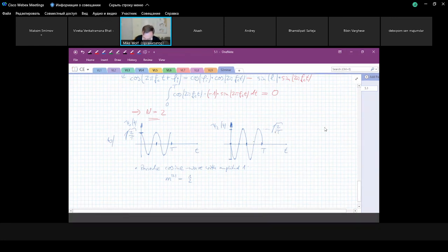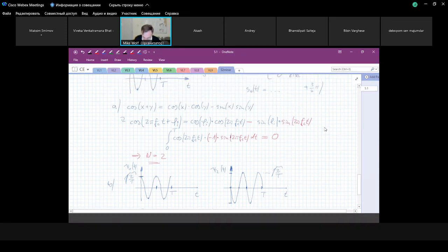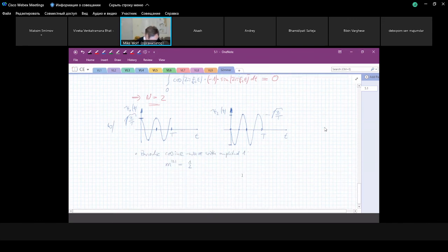So now we have the orthogonal basis functions, and we don't need more. We can use both basis functions, which are orthogonal, and the linear combination of these is just our signal. What we see here is basically psi1 of t in this interval. If we weight psi1 of t with square root of 2 by T, then it's exactly a cosine. And this minus sine is a weighted version of the second basis function. And therefore, we can easily obtain the signal vectors.